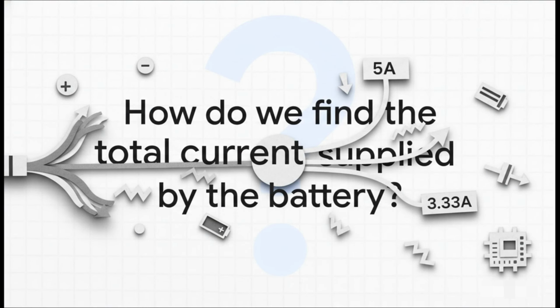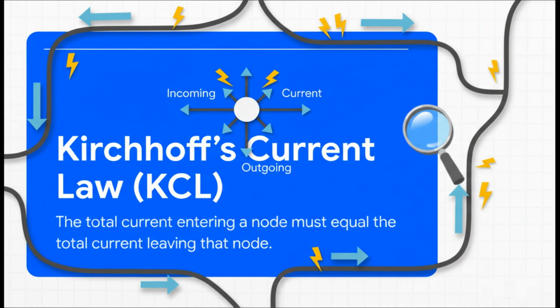So think about it. If we know that 5 amps went down one path and about 3.33 amps went down the other, well, how do we find the total amount of current that came into that intersection in the first place? And the answer comes from Kirchhoff's current law, or KCL. It's really just a law of conservation. It basically says that whatever current flows into a junction has to be the same amount of current that flows out. You can't just lose current. It doesn't just disappear into thin air.